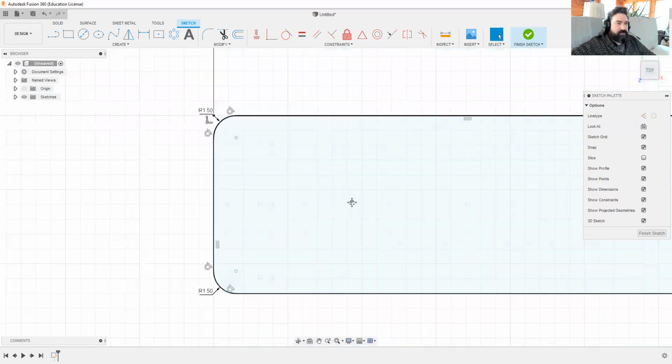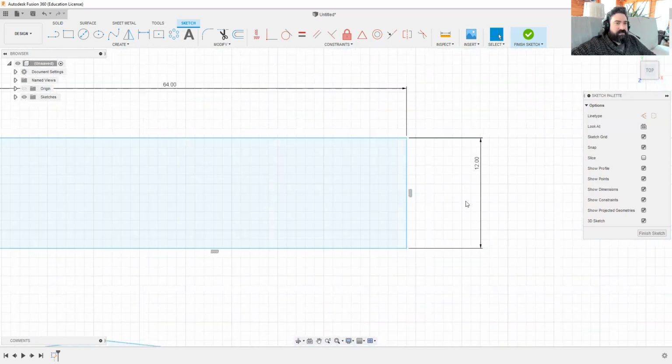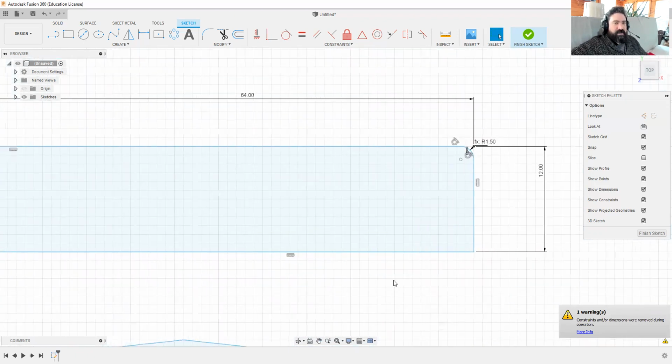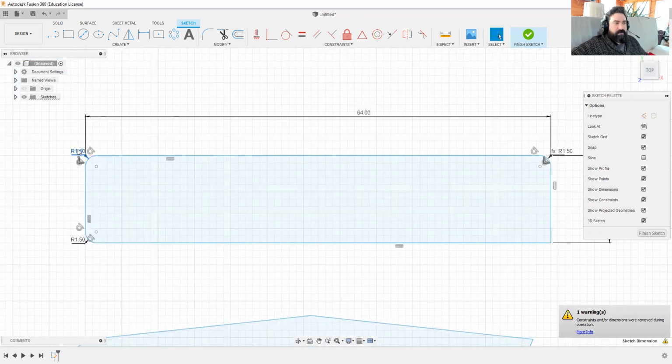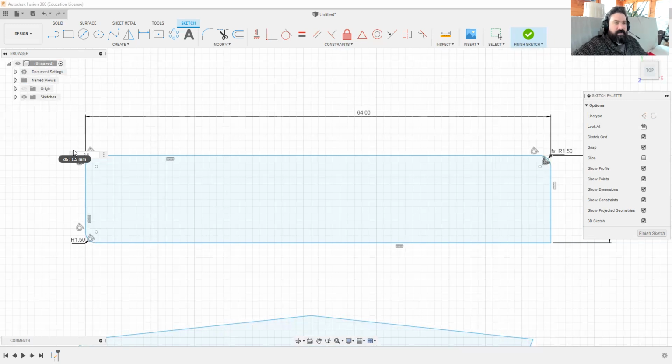So what I could do is I'll repeat the fillet tool. Oops, now it's on delete. I'll repeat the fillet tool here, but instead of adding a number, I'm going to type in lowercase d6. Now you see it changed to that point. It's a reference now. So now if I went back, double clicked on the number and changed that one, let's make it 2.5. Now it automatically changed that one too, but not this one.